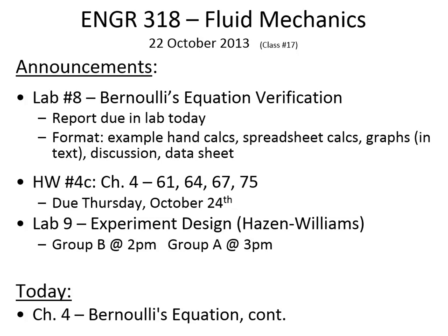Now, what I'm expecting to see, the curve should look like: here was a point, then it went down a little, and then maybe it went back up again. That's sort of the theoretical curve of the HGL. In reality, since there are energy losses in there, it'll probably look more like that, possibly, for the HGL, hydraulic grade line.